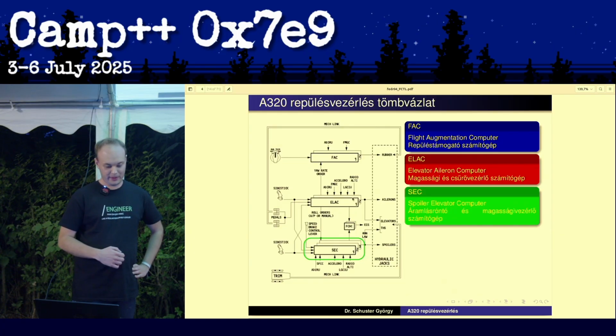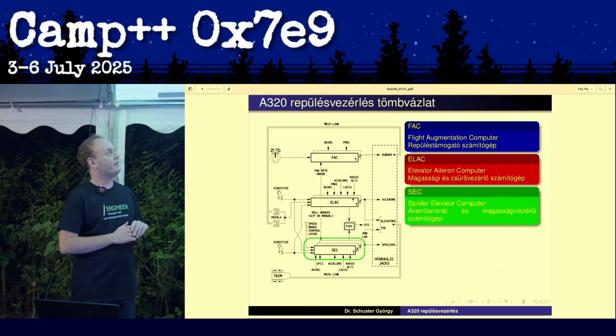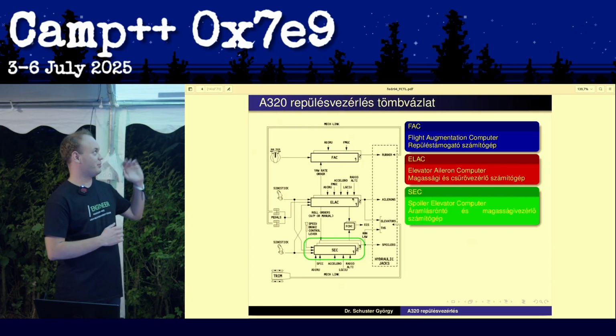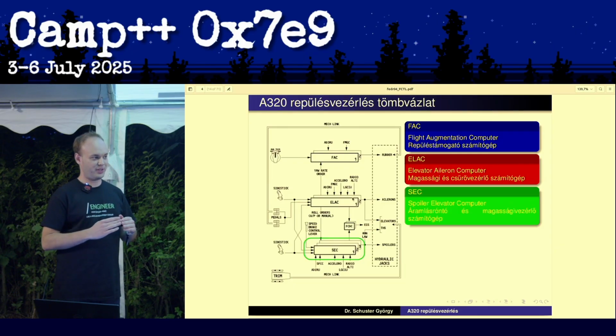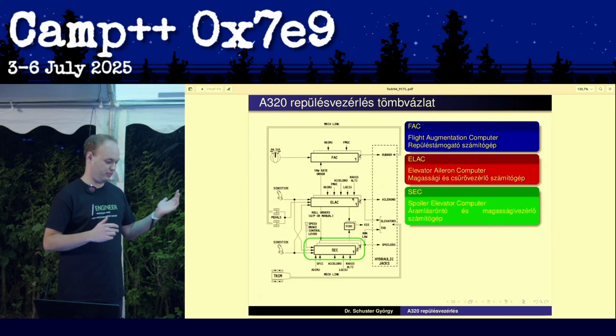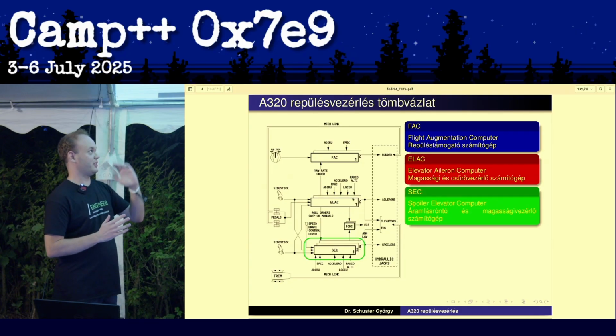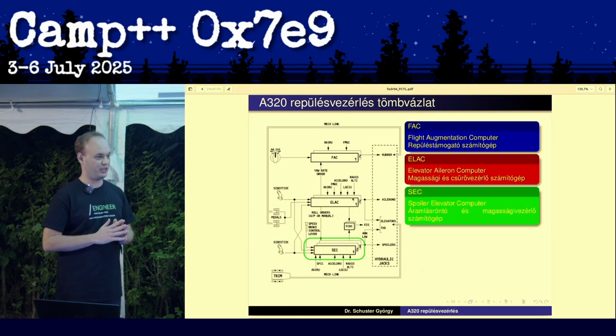It is not the exact implementation here, but in general, you have something called a 2 out of 3 operation, where you need valid outputs or inputs from, let's say, sensors out of the three existing ones to continue operation.